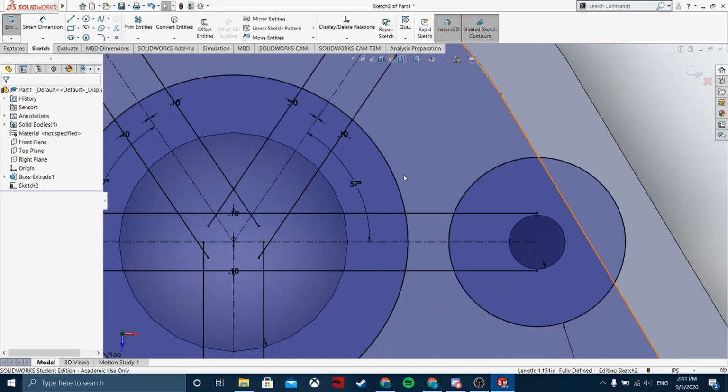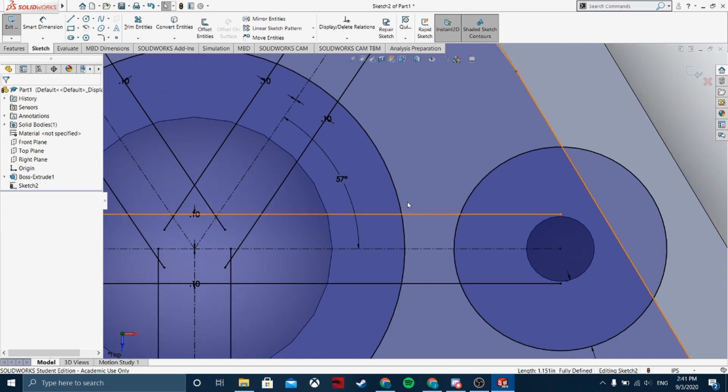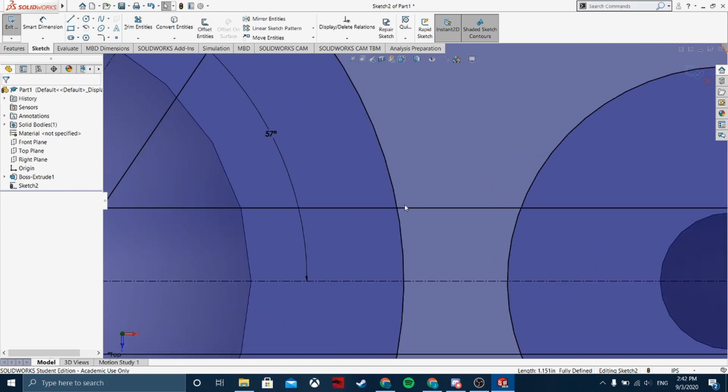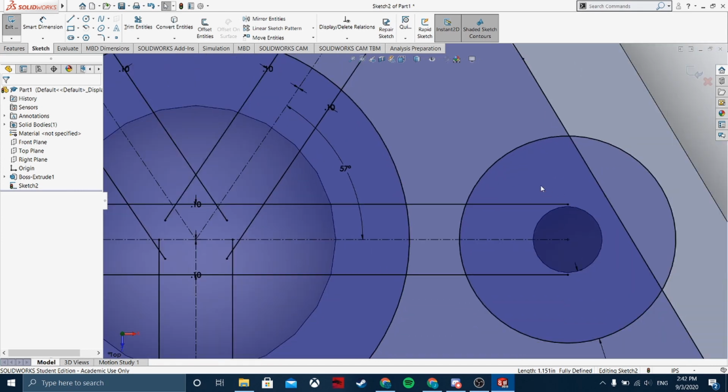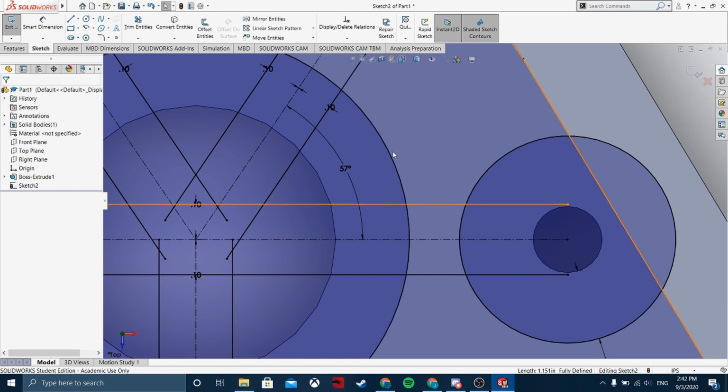If we make the fillet diameter a quarter inch, so the radius would be 0.125, using these two corners that are so close together, the fillet command would make a curve, but then it would have some sort of sharp edge here and make another curve here, right?